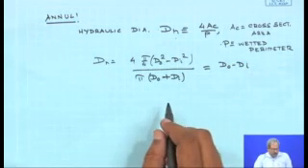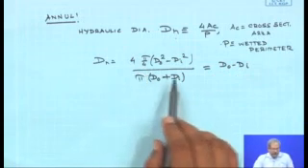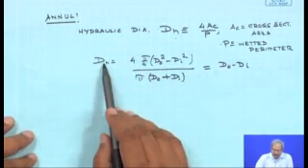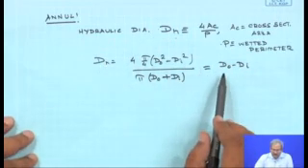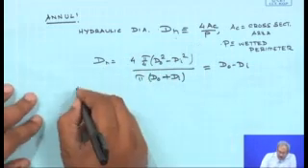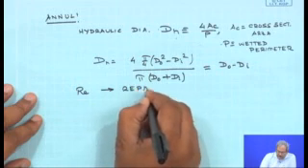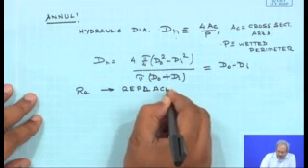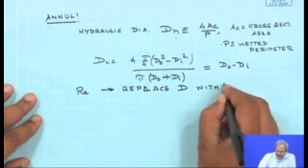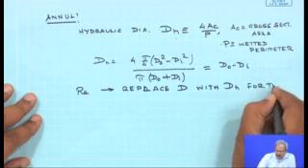So, for turbulent flow, in the Reynolds number, replace d with the hydraulic diameter for the annular region.